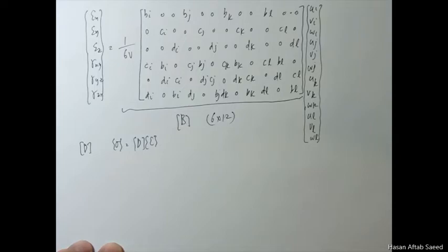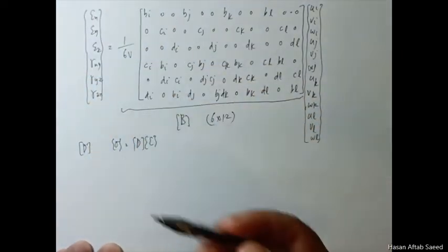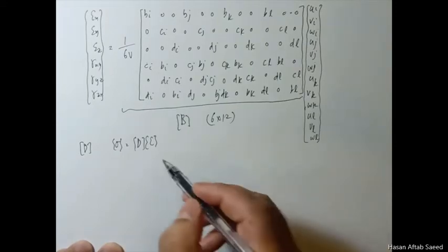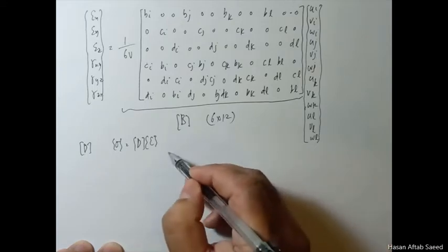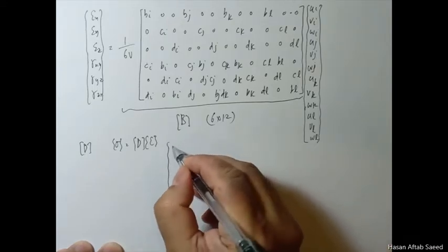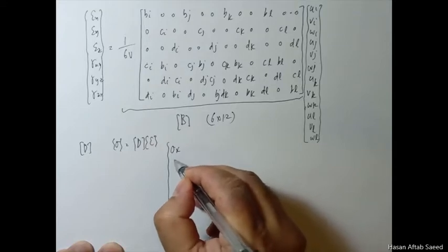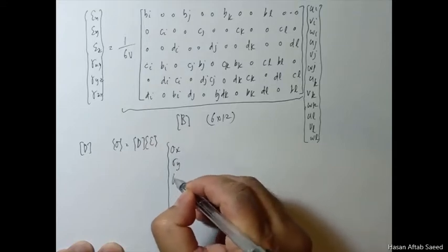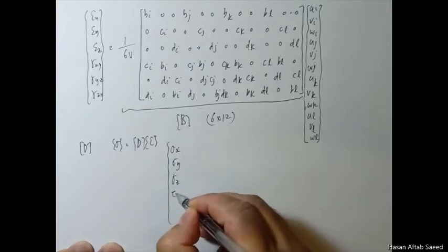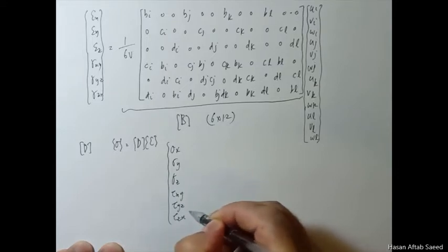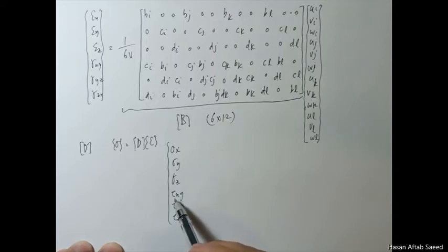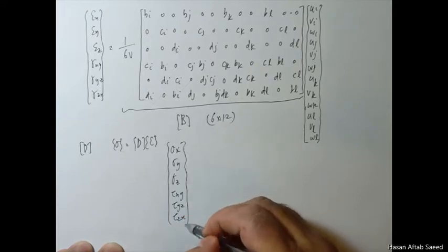Now here again you have 6 strain components, so you have 6 stress components as well. Actually they are 9, but 6 are unique ones, the other 3 are just the same, if you recall the complementary property of shear. We have tau xy, tau yz, tau zx. We are talking about tau xy and tau yx, these are the same. Similarly here, so just 6 should suffice.